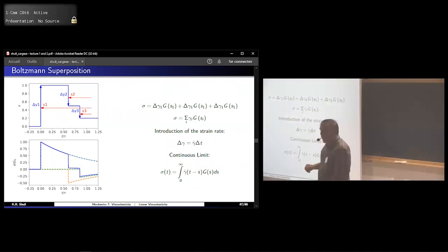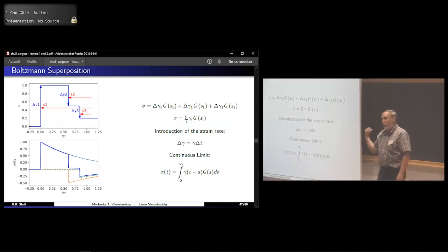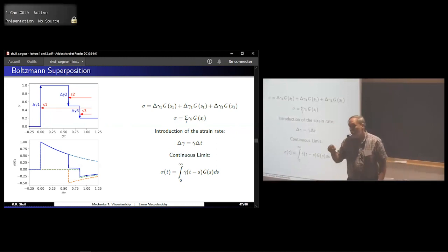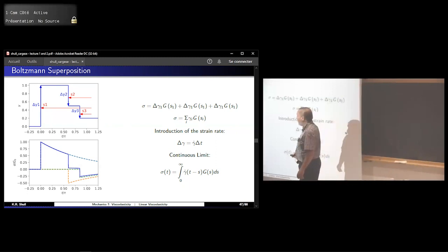Probably Michael would be able to tell us what, but it has to decrease with time. And when we start talking about frequency-dependent modulus, the magnitude of that has to increase with frequency for similar reasons. So it's got to relax. It can't go up. Yeah, you would basically be creating energy if you increased with time.